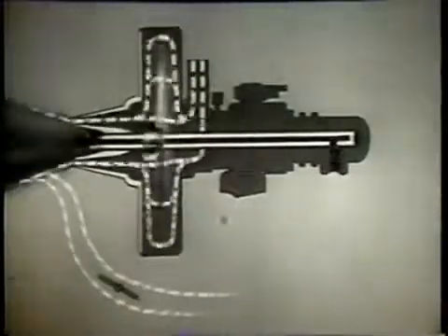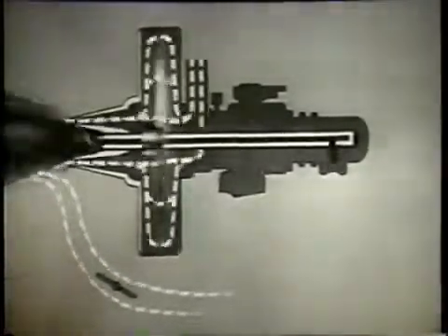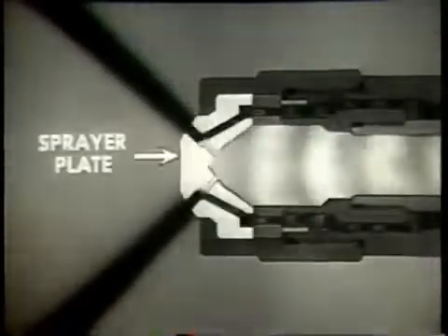In the rotating cup burner, the action of the rotating cup and the air from the blower atomizes the oil. Additional air enters through the damper door. In the steam atomizer, oil under low pressure is heated by the steam passing through the barrel and is atomized at the sprayer plate. The register gives the air from the blower a rotating motion and mixes the air with the oil.